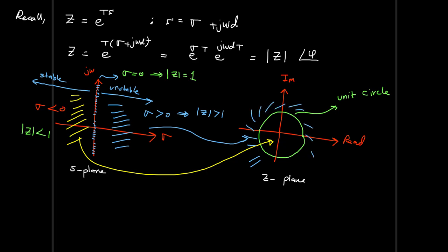So simply, if I need to check the stability, someone will say, if I can find the exact location of the roots of the characteristic equation, which is here 1 plus GH of z equal to 0, if we can find the z's, the poles, which equal z_j, if those are located inside the unit circle, the system will be stable.